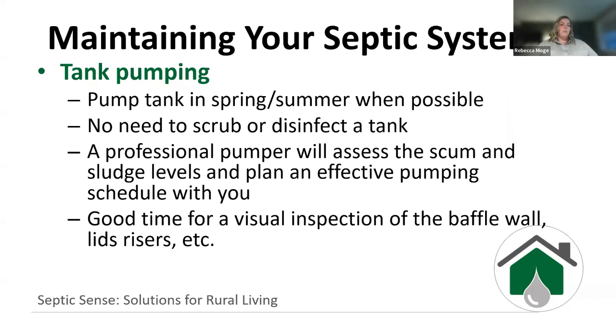When to pump your tank. We recommend in the spring or summer when possible, just because we want to keep the heat in the tank. That again contributes to the bacteria and the separation there. So in the spring and summer, if we can. We don't need to scrub or disinfect a tank. When we have a pumper come out, they'll assess the scum and the sludge levels. Usually most will leave a couple inches of the sludge at the bottom of the tank, which assists in the bacteria recovery for it to then start over and continue on with the cleaning of our effluent in our initial treatment.